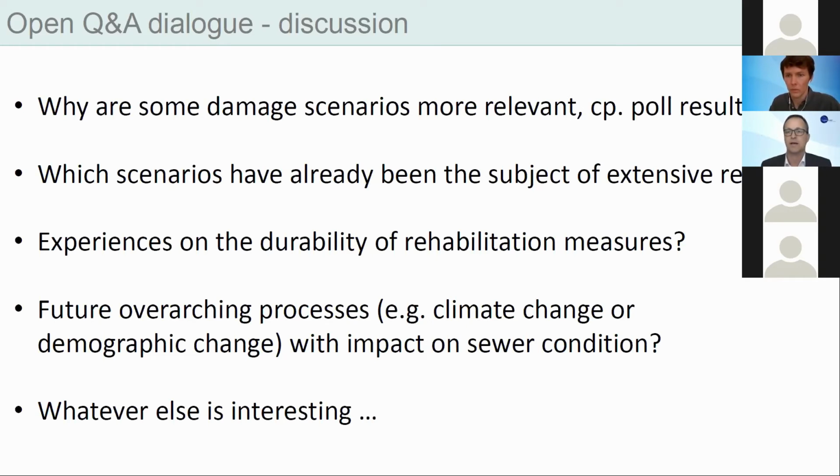It doesn't depend. For smaller sewers, we have also tried, so for 200 or 300 millimeters, but then it's more flexible pipes, because the deformation of rigid pipes is very, very low, and we don't want to crack them, of course. We just want to measure the stiffness of the pipe-soil system. So it can be applied. The main application is really large sewers, and there it's also worth it, because it's quite costly if you have any larger damages, or even breakdowns of the sewers. It's high risk, so it's really worth doing more than just an optical inspection, to also check if the soil and the pipe, the whole system, is like it was assumed in the design.